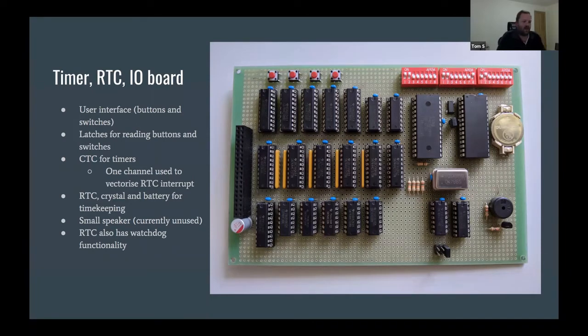Whereas if you hook that into a Z80 CTC channel configured as a down counter, and load the channel with a value of 1, then when the RTC generates an interrupt, the CTC channel decrements to 0 and raises an interrupt, and will then be able to supply a vector, which you can use to branch straight into the code you need to service that interrupt. So that's quite nice. That's a little trick that I learned along the way.